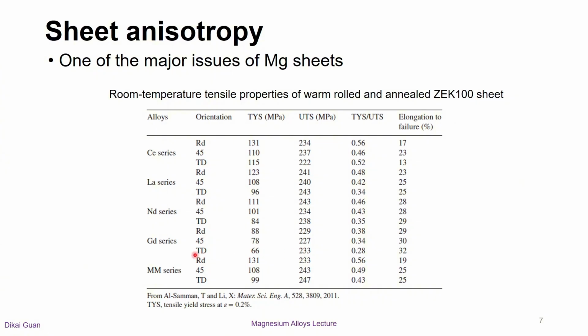The neodymium additions lead to isotropic ductility, 0.28 for the RD and 45 direction, and 0.29 for the TD. All these mechanical property changes can be correlated with the microstructure, for example, texture.